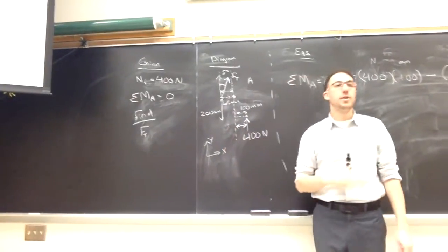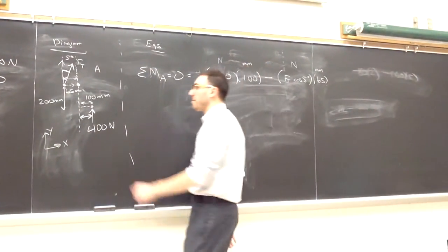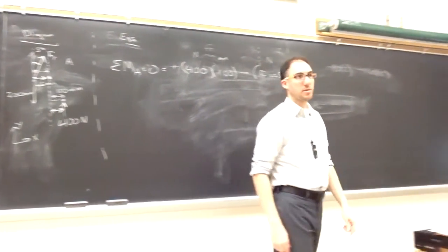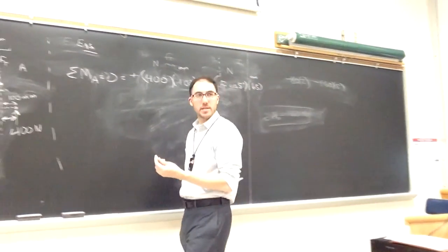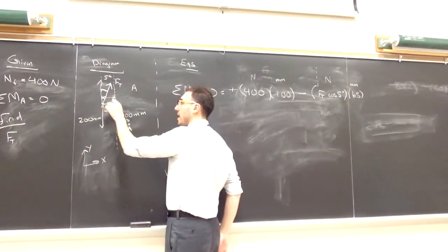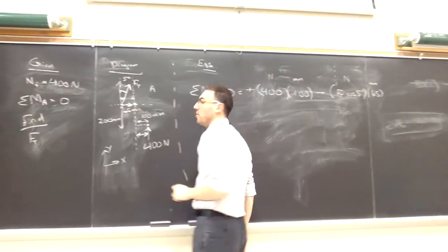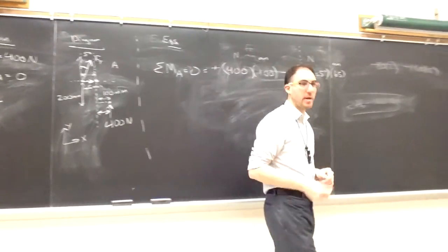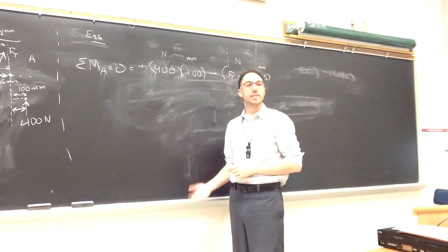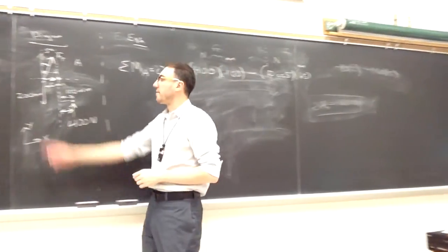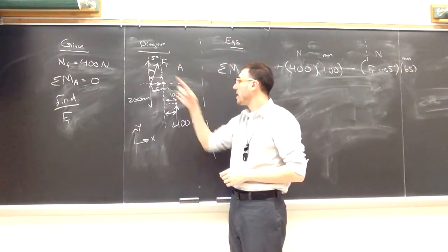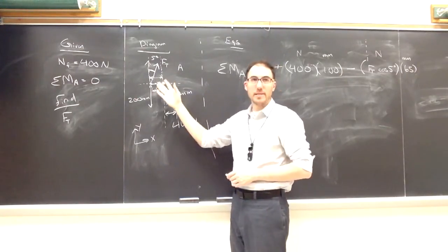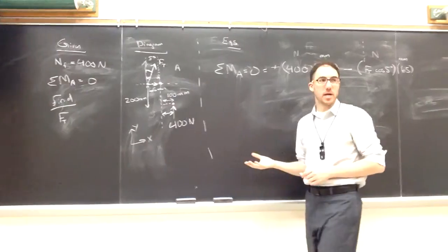I also then have the horizontal component. So what will the moment contribution be for the horizontal part of the Achilles tendon force? Right? It's going to be 0 because it acts along this line, and that line passes through point A. So its perpendicular distance to point A is going to be 0, in which case its moment contribution is also going to be 0. Right? So the vertical component of the tendon force and the ground reaction force both contributed to a moment around A. This horizontal component did not, and the reaction force did not have a horizontal component.